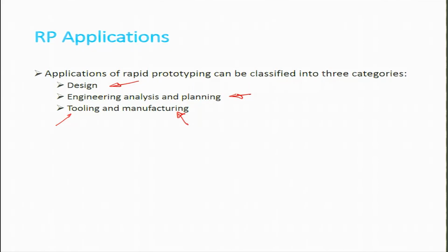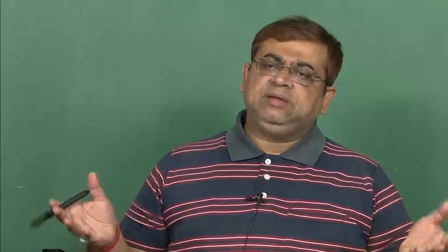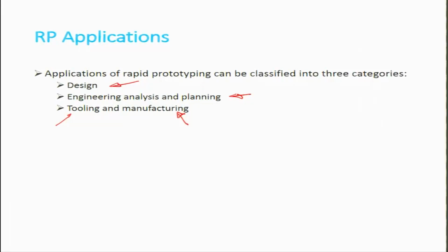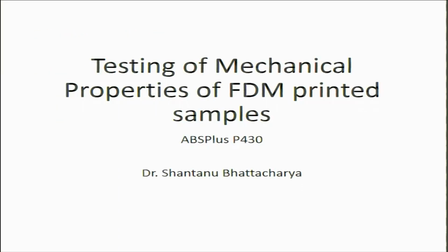Many times in prosthetics, when you are building up an artificial leg using a polymer, using injection molding techniques, it is probably a wise idea to do this iteratively to see from a die shape if we can pull out the negative of the cap geometry. Is it really going to be the part which is intended to get manufactured? So before realizing the die, you could actually build up this geometry and see if it is working out before going ahead and CNC machining the die so that it can be put into the injection mold. So such are the interventions that RP has, particularly solid free-form RP, in development of manufacturing processes.